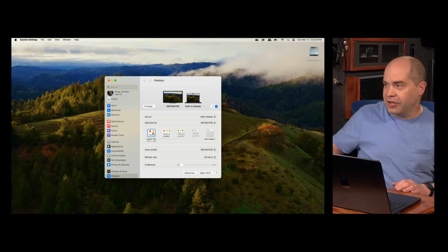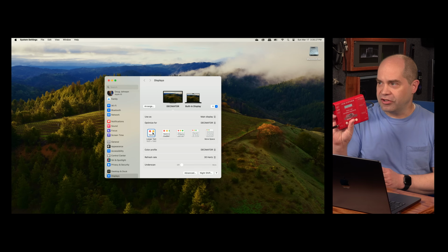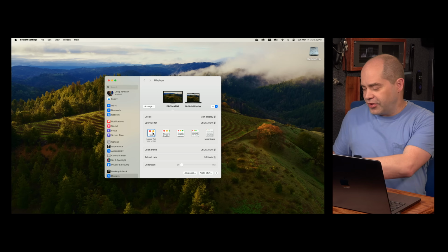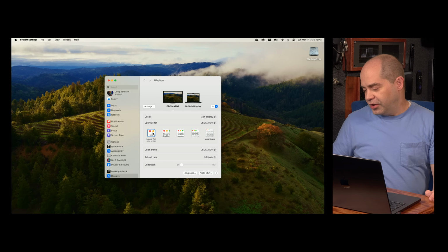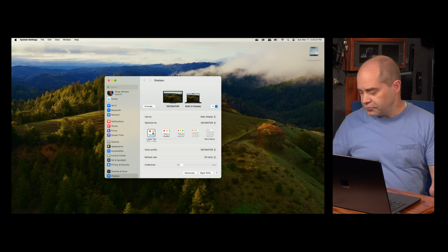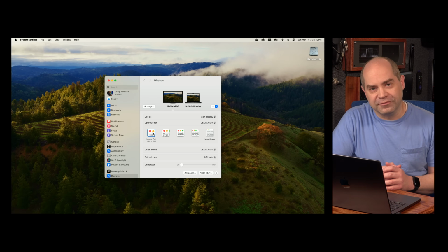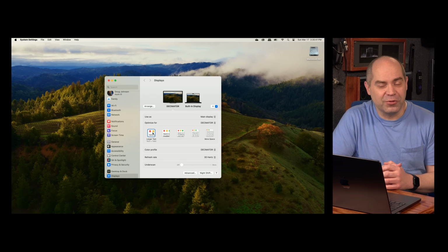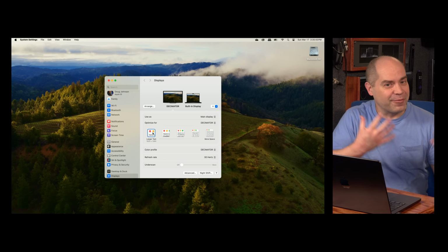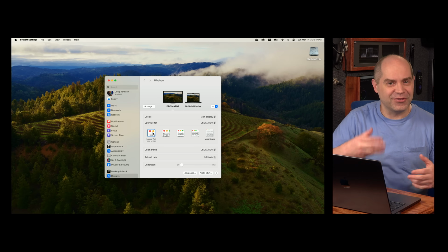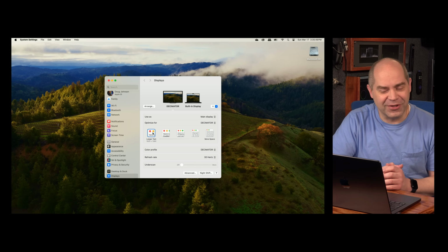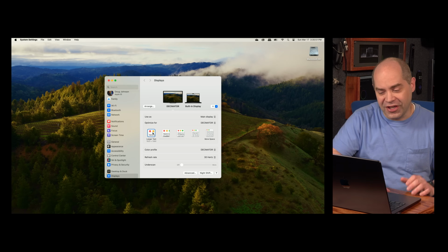If I take a look at my Decimator, which I've got hooked up here, it has a display on it that says what signal it's receiving. In this case, it's receiving a signal that is 6G 2160 30p. Well, my switcher is running 2160 at 29.97, so the frame rate's a little bit different. Even though it's a small difference, it's enough that my switcher would not allow me to display a signal whatsoever. So it'd be nice to be able to change that.